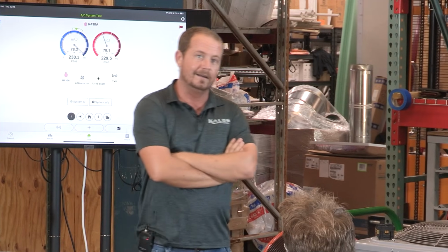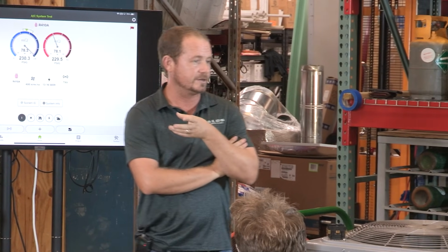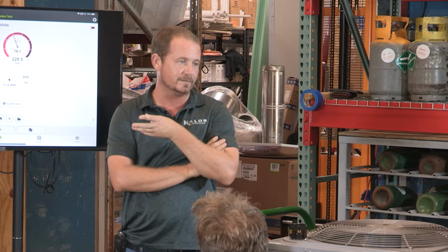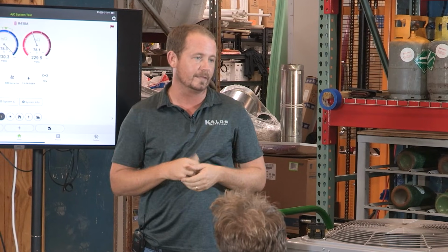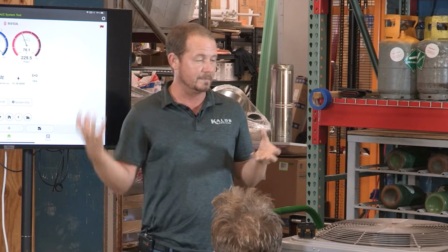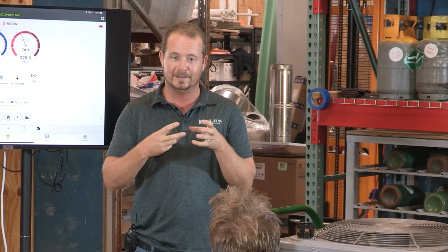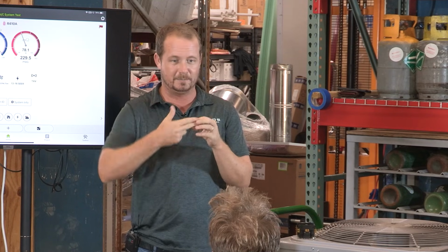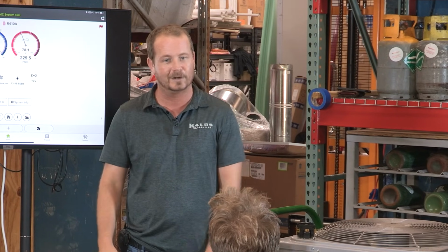You know how to change the direction on a 3-phase motor? You just switch any 2 legs, right? So I thought, oh, well, an ECM motor is a 3-phase motor. So I pulled the end bell off, the motor module. I took the 3 wires and I just switched the pins. I pulled them out and just swapped them, and then it ran the right direction.